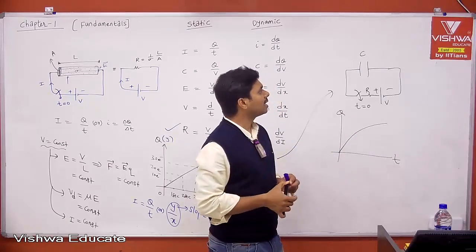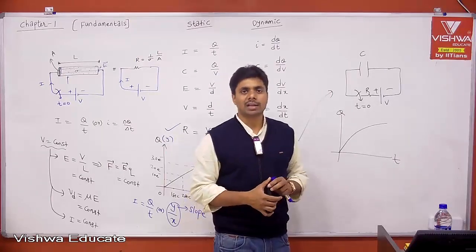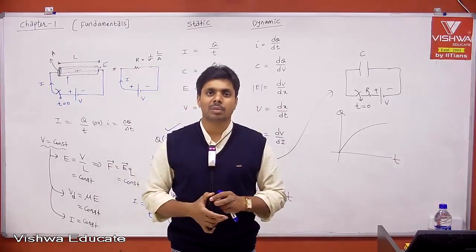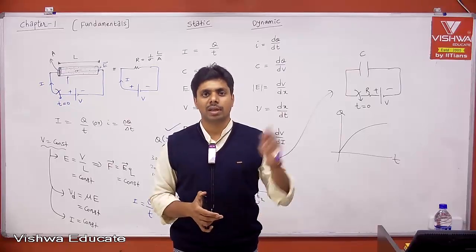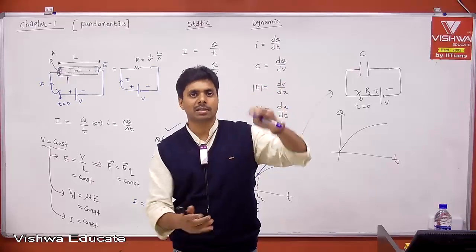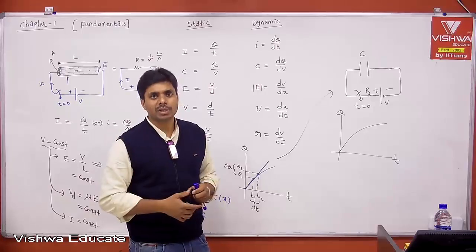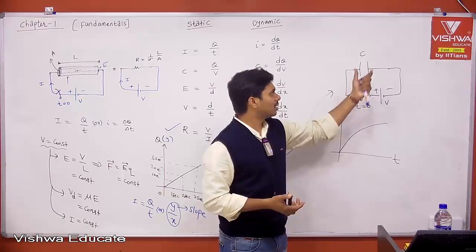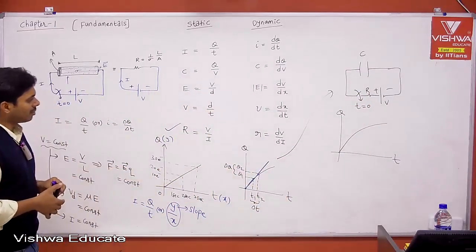Okay, but I'll explain a little bit about the capacitor later on, because if you understand capacitor action very well, I can say 50% of MOSFET operation is over, because basically a MOSFET is nothing but a capacitor between gate and bulk, and we see capacitance action. But in the case of a MOSFET, metal oxide semiconductor, there are two plates, one is metal and another is semiconductor. But if you take a parallel plate capacitor, both are conducting plates. If time permits, I'll explain the capacitor operation and try to correlate it to MOSFET action also. Okay, fine. I hope everyone understood.